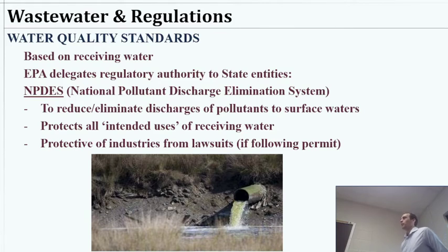So sometimes we'll have a technological standard, but primarily we do it based on water quality standards, which are developed based on the receiving water. So discharging into a very clean, quiet, slow-flowing, small flow rate stream is much different than discharging into the Mississippi River, because the two different waters have different assimilation capacities. For one, how much of an impact are you having on the actual chemistry there, and given that amount of impact, you would want to look at what kind of wildlife and things are there. So there's going to be some sort of ecological assessment for large discharges.